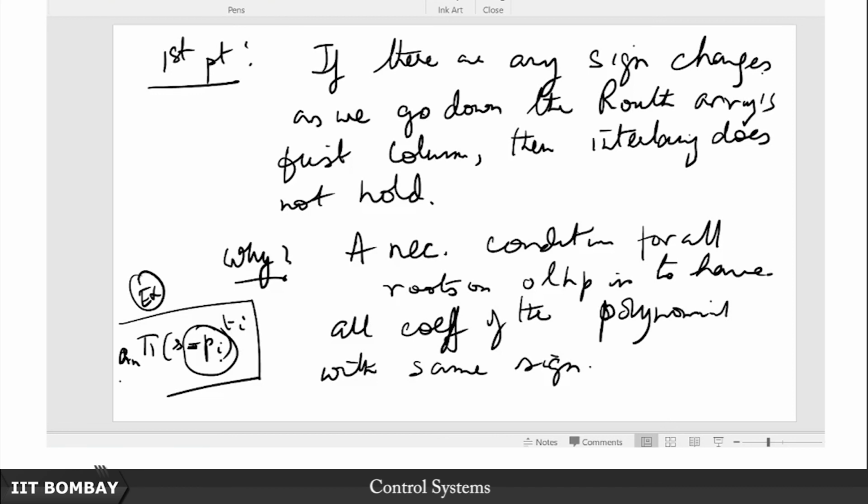And this now also reveals why in the previous lecture, when we talked about an being positive, we said that the Mikhailov plot evolves from the positive real axis. At omega equal to 0, it starts from the positive real axis if an is positive, because if an is positive then by default a0 is positive, and a0 is after all the value of this polynomial at omega equal to 0. So that is one crucial aspect that I really thought merited some clarification.